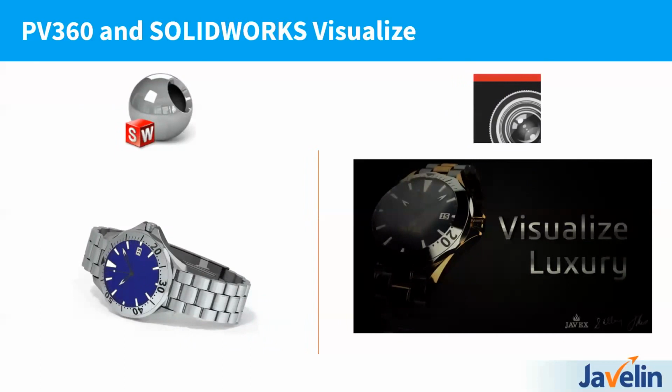Okay, so I'm not saying that you have to use PhotoView 360 for just the iterative stuff, and not saying that you have to use Visualize for just the end-use stuff. At the end of the day, whatever you're more comfortable using and whatever you like better, they're both very good tools. The only advantages for end-use stuff that Visualize has over PhotoView 360 is that it is a non-biased rendering engine, so you are going to get more realistic results in it, and it does have that GPU rendering as well, which should get you faster renders at the end of the day.